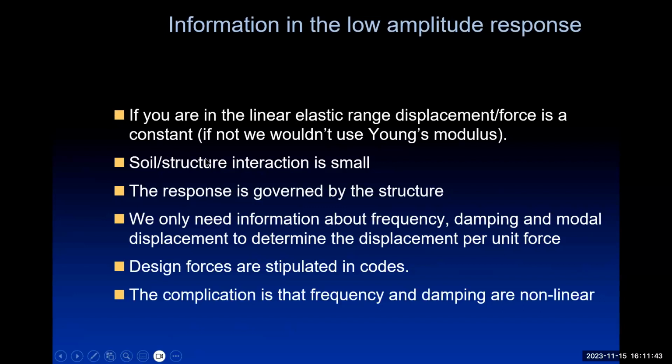So if you're looking at the behavior of an entire structure and you're looking at very small vibrations, you exclude soil structure interaction because that only occurs at higher frequencies, and you have Young's modulus or its equivalent working for you. You get the displacement per unit force characteristic, which is a constant all the way up to the end of the elastic range.